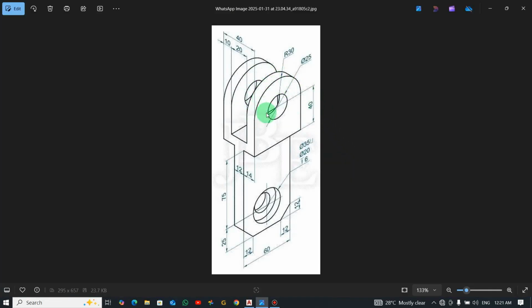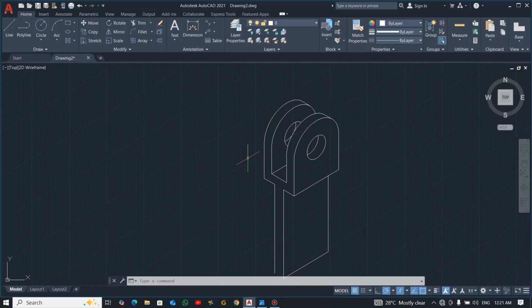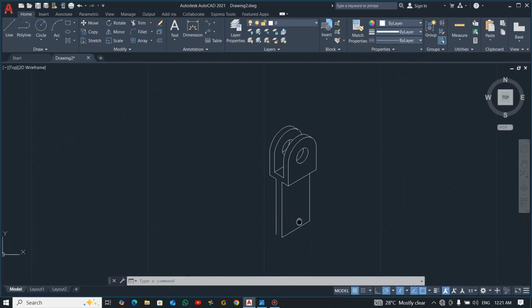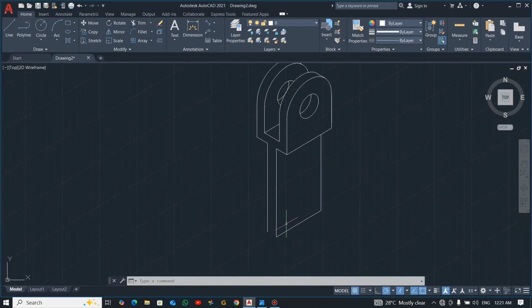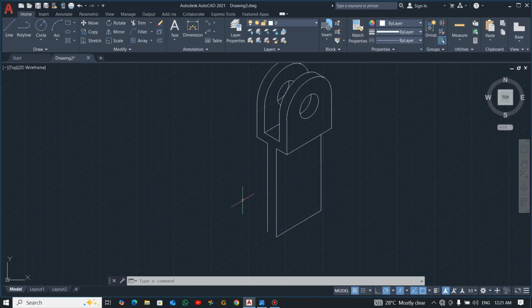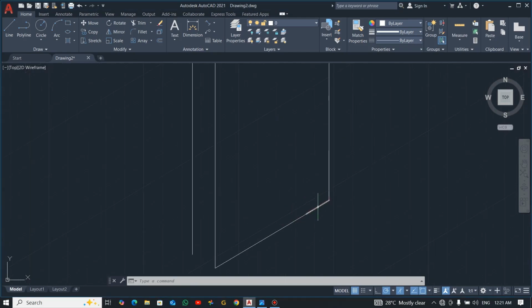Nothing is supposed to be done here. We are done at the top. Now we need to focus at the down here. So for the down, now you can see this chamfer is at a distance of 12. Alright, so how do we do that? Remember, we drew a line of 12 already here, so you can just pick a line command, bring the cursor to this corner, move up, don't click, enter 12, to move to the location.